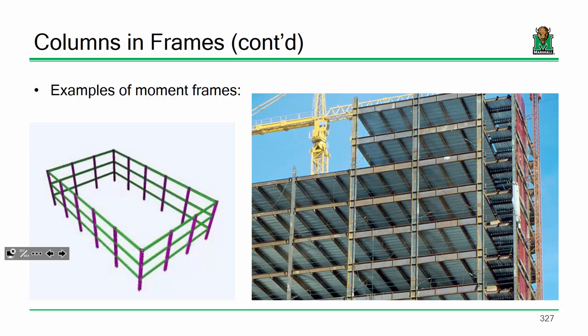The same thing with the beams. These beams I would treat as simply supported. These beams would be fixed into a frame, and in order to accurately get the moments and shears in these beams, I'd have to break out RISA and do a big RISA analysis, or something like moment distribution, because on this side these are all simply supported beams. This is a highly indeterminate system. Does everybody kind of remember that? All right. Everybody good so far?